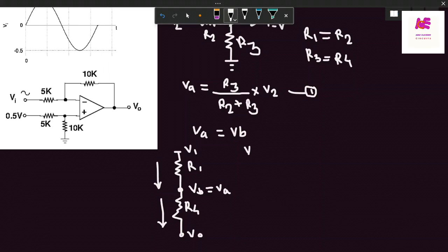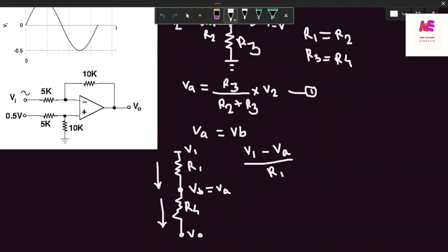So apply KCL. I uploaded a video regarding KCL and KVL. If you don't know how to apply it, please go through that video. I'm providing the link in the description box. V is equal to IR, simply we are applying. So here the current is V1 minus VA divided by R1, since I is equal to V by R. This incoming current is equal to the outgoing current, VA minus V0 by R4.